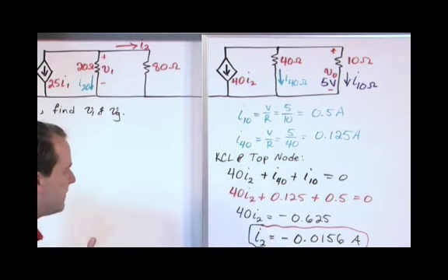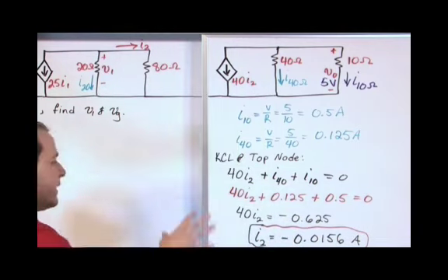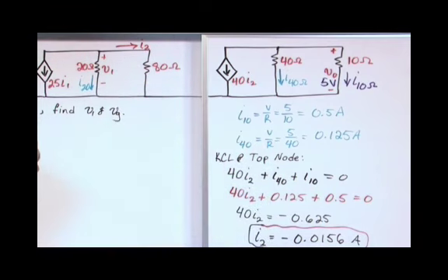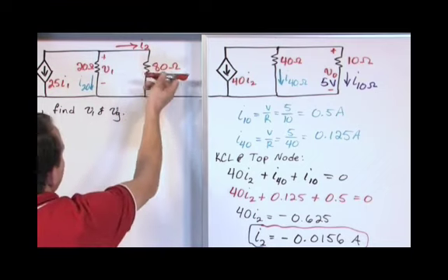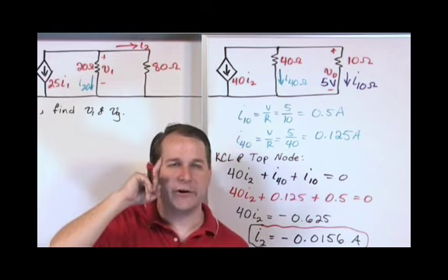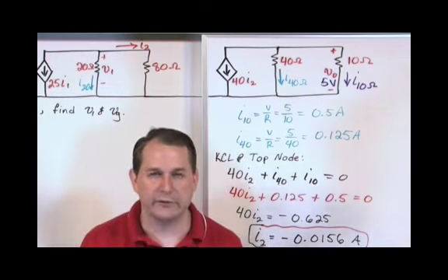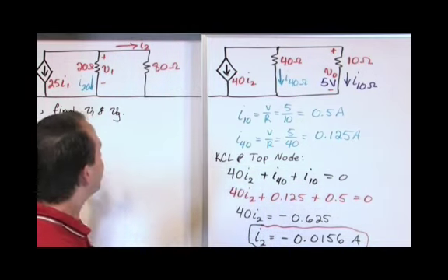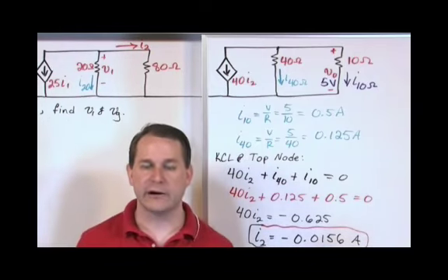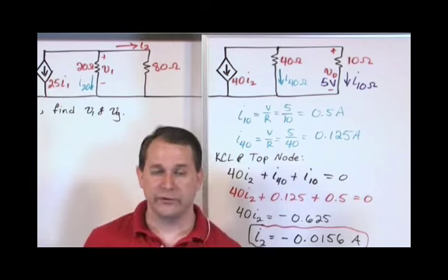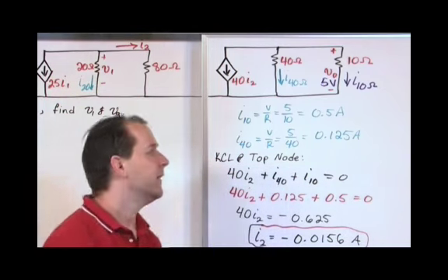So this value of the current is negative. Now what does this really mean? We've talked about this. If you get negative currents, it just means that the direction that you've drawn everything is really backwards. So if you really construct this circuit, I sub 2 is not really going this way. I sub 2 is really flipped around the other way. But that's just something we keep up here. We don't modify our drawings. We don't flip the direction of the arrow because that would be a disaster. We've already written equations assuming that the directions are like this. We get negative numbers, it just means that we were backwards on the way we drew it. It doesn't mean we have to change our drawing.